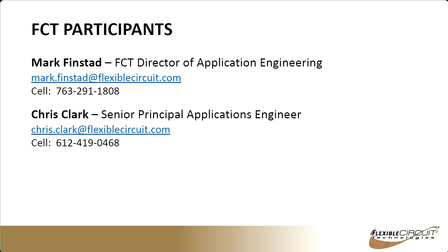What are the benefits of having aluminum backing? We did discuss this briefly. It is a very inexpensive way. The aluminum that we put on is not very thick, only a couple of mils thick, so it's very inexpensive and an easy process. It goes between your heat sink and your heating element, and that allows the heat to be spread out over a larger area.